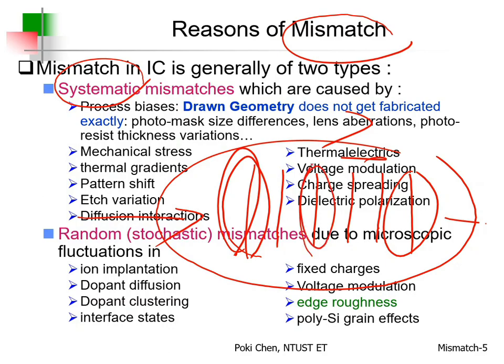For the same wafer, because oxygen needs to diffuse in, right? Then to the middle, they can get oxidation. So according to thickness, thicker to the boundary, thinner in the central area, right? I told you, the thickness always looks like that, right? That's it.